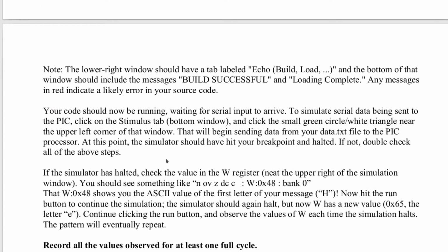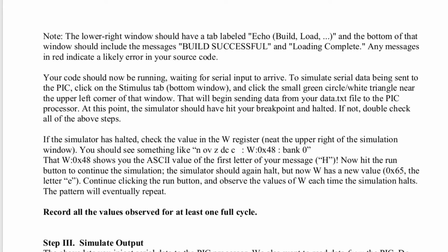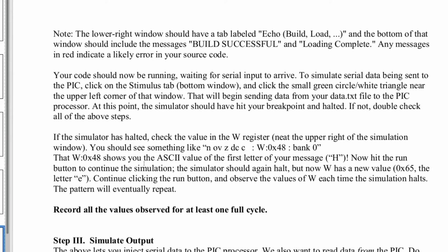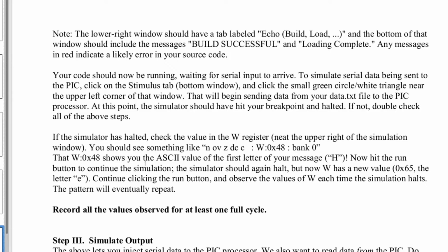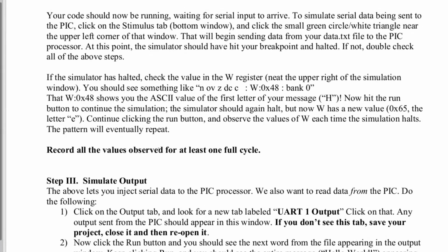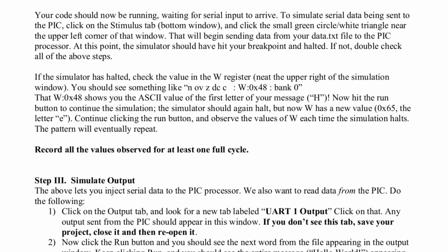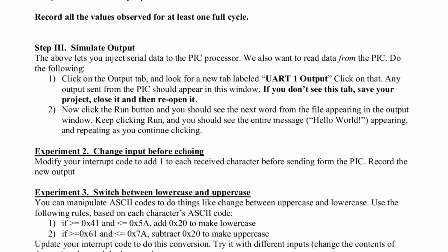All right, build it up and run it, and what you should see is that as you run through your code, each time that you read from the special function register for receiving a character, you should see the successive characters of hello world or whatever you put inside your test file. All right, so record all the values observed for at least one full cycle. That's simulating input to the PIC processor.